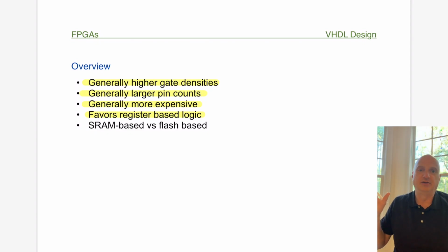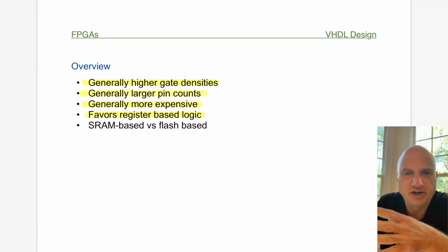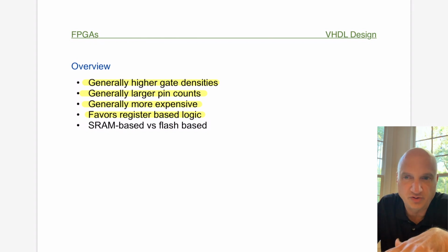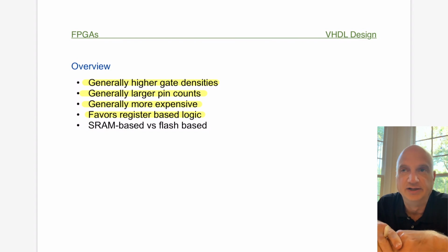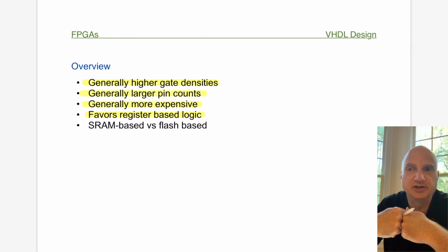Now, in the old days, the FPGAs primarily were SRAM devices, which meant that internally the configuration for an FPGA was done by programming ones and zeros into SRAM elements to control the hardware connections internally. What that meant was that when the power went away, the design went away. So you had to constantly load the design in, and that's still the case today with most FPGAs.